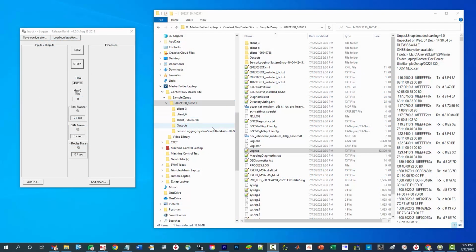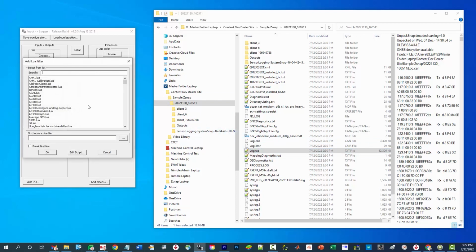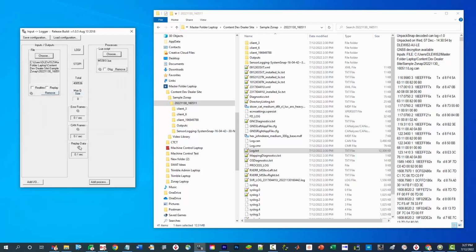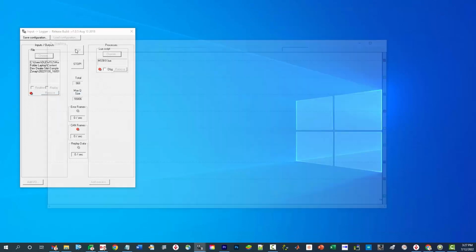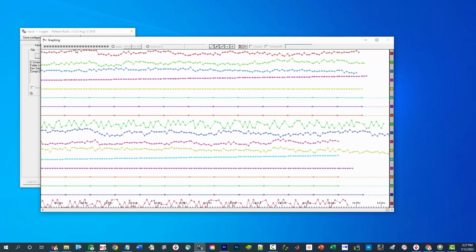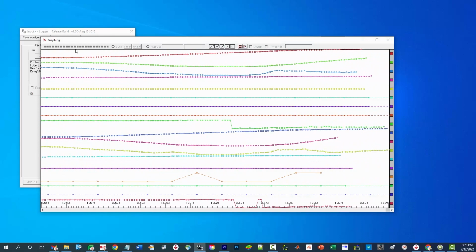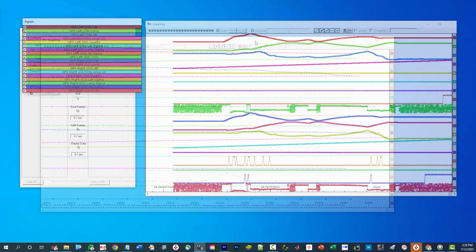A program is used to plot the sensor data. In this example, the GNSS receiver sensor data is checked for possible problems. The log will help identify the state of the receiver at the time the data was captured, showing a fixed position or autonomous. The log will also help identify if there was a CAN issue, showing gaps in the GNSS CAN data, indicating a possible CAN bus issue.